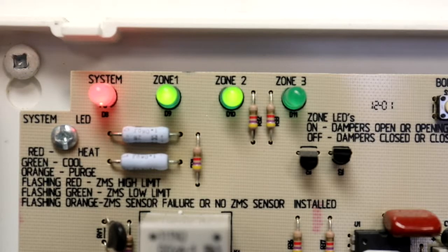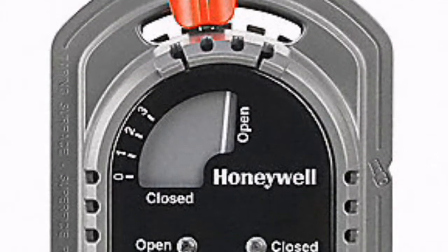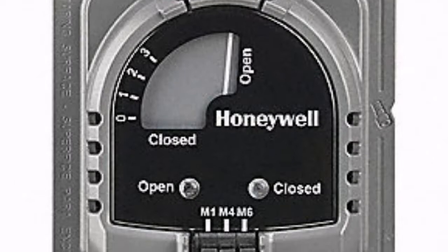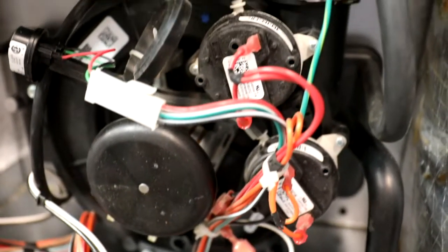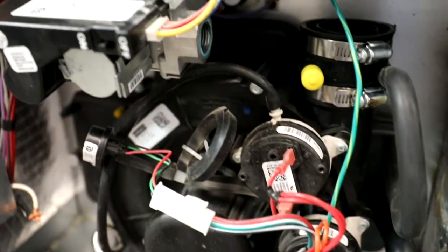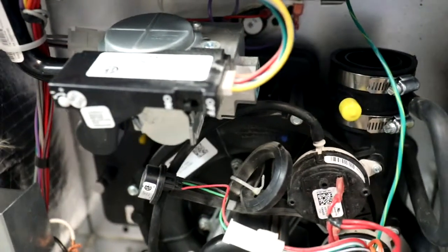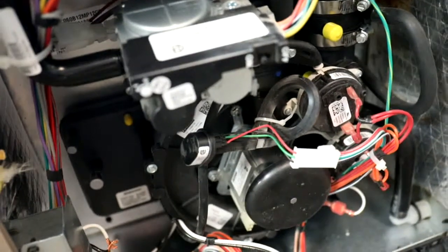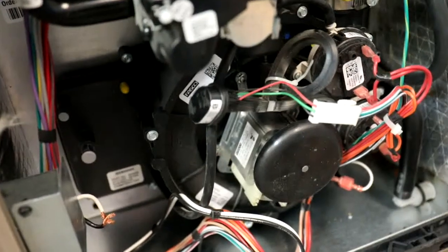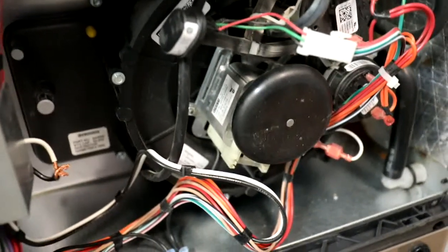When more than one zone opens, the pressure is relieved and the bypass automatically closes. For a proportional zone control system, when only one zone is operating, the zone control panel partially opens the other zones to relieve the pressure. With top-of-the-line modulating furnace and AC equipment, neither a barometric bypass nor a proportional zone control is needed, because the equipment automatically adjusts to the appropriate output level based upon the number of zones calling for heat or cool.